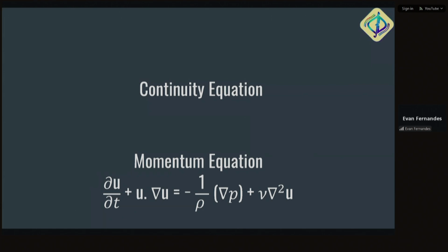You can think of it as if you have a flow and in that you're introducing ink, like an ink jet. That ink jet is not going to be manipulating or disturbing the flow that you've already set. You're first initializing your flow and then introducing an external parameter, and you just want to see how that external parameter is going to be transported in your domain from point A to point B.